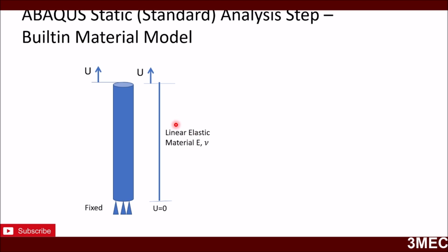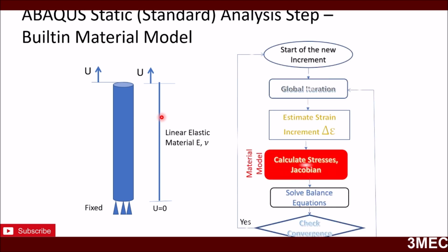Another simplistic way would be to use a truss member, because it's an example of a truss element, so you can model it as a truss member as shown here, and again you can do the same thing and estimate the stresses and everything in your truss model. This will save a lot of time. So depending on the problem, you can do that. Again, if you're not familiar with ABAQUS, I would suggest you look at the ABAQUS courses on my YouTube channel.